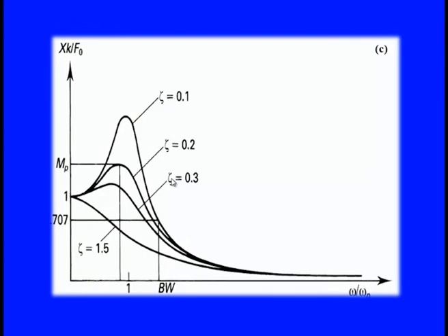But again you see here we cannot go for a higher damping value blindly, because we need to see whether we want an effective solution in the minimum time or we just want to delay things. So, when zeta is 1.5, you can see that the responses are just going, and the steady state response is just diminishing, or going to the end in a very long time.